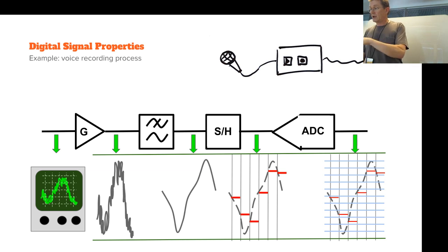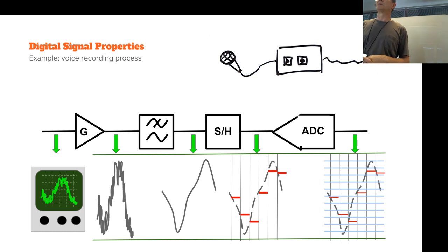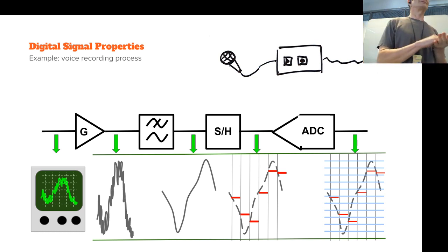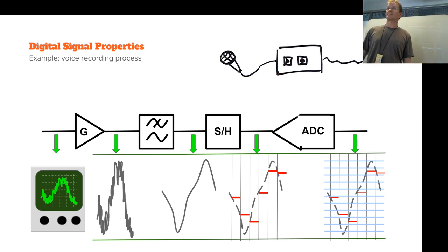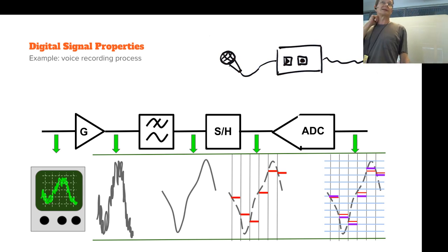And at the end, the A to D conversion actually just quantizes the levels. There's no half bits or quarter bits on the A to D conversion. Believe me. Some people actually try to increase the resolution by starting the averaging. Yes, you have averaging. You may have these decimal bits, but they don't mean anything. If they did, the chip manufacturer would have sold the device with higher bits for better profit. Okay, but anyways, so quantization, meaning the nearest value will be then selected, something like that. Usually it's actually either higher value or lower value because of the electronics.